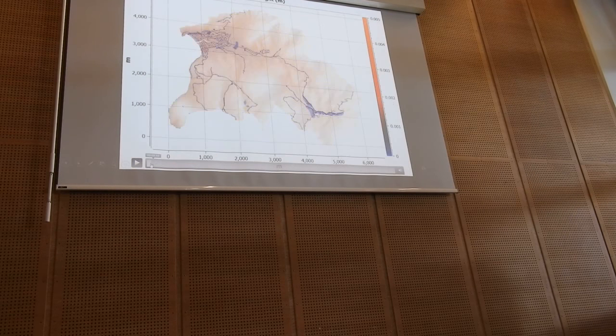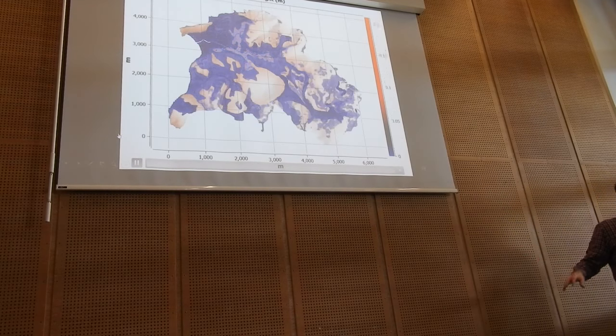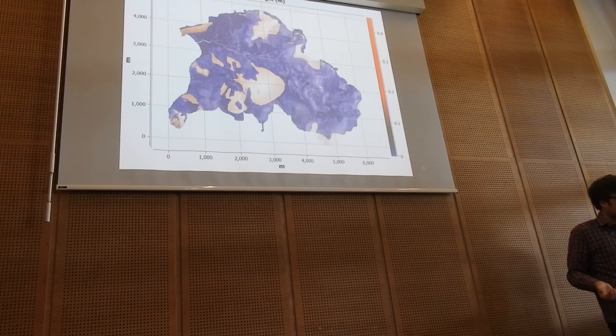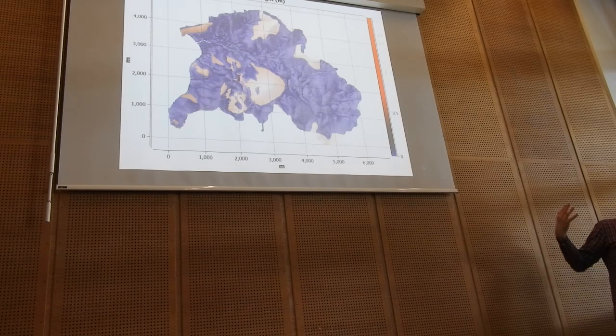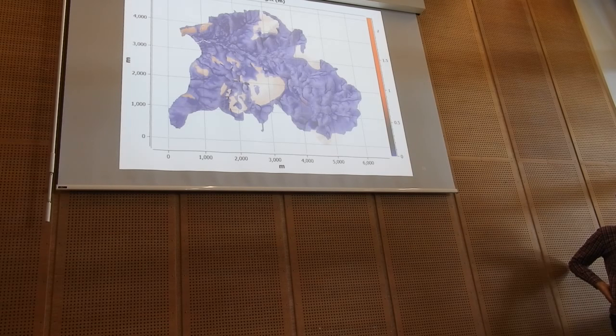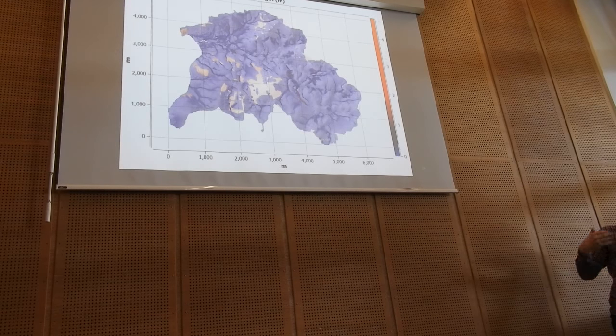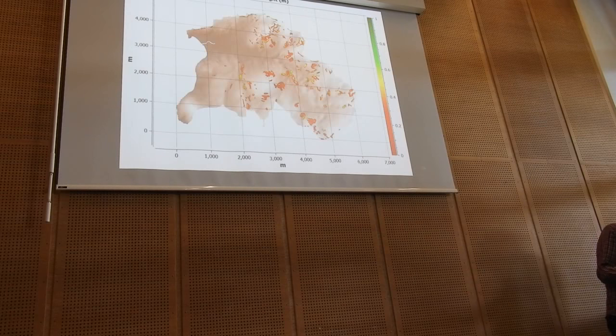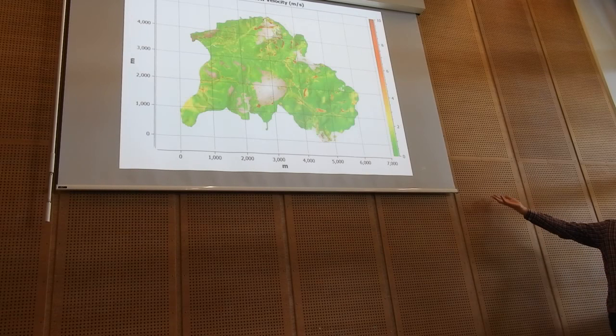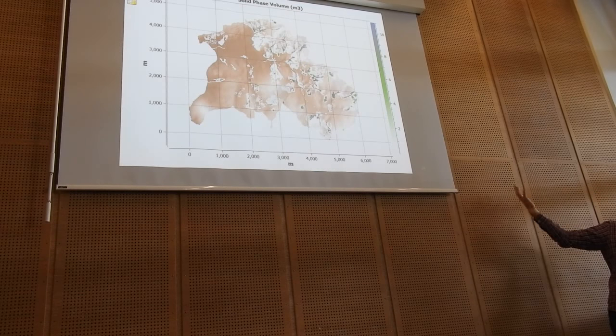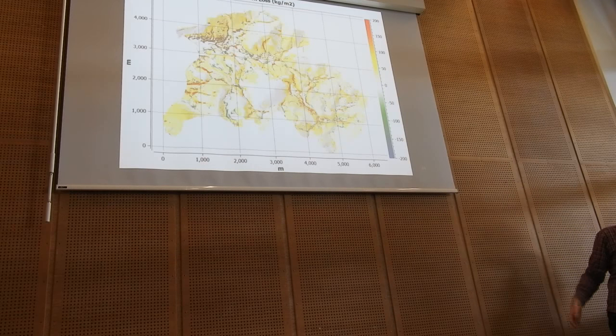It's a bit quick, let me play this again. So at the start, everything infiltrates. This is a hurricane, so it's quite a lot of rainfall, so it's a big event. You get some flooding, the slope failures are slowly added. You see here and there some shallow failures popping up. And then the runout mixes with the water or it blocks channel flow. This is the failure heights in total, the flow velocities, the actual solid material, so the debris flows itself, and this is the erosion and deposition.